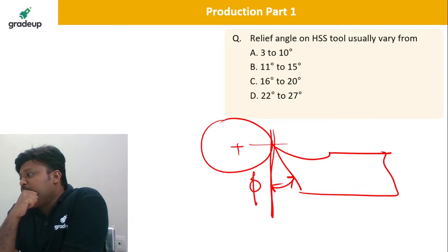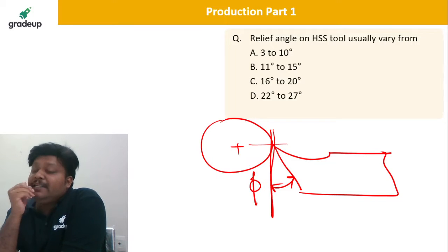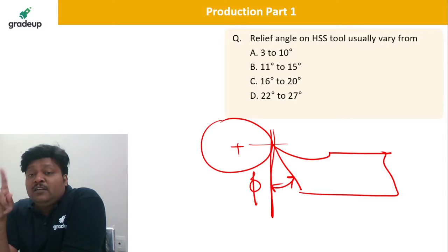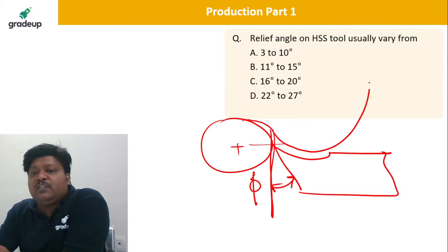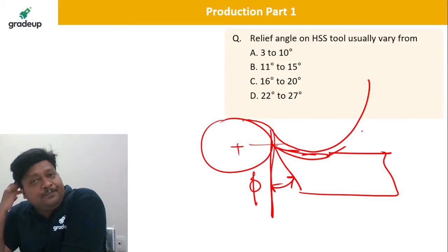Question is like this: tool cutting forces with increasing cutting speed will be, options are increase, decrease. So dear, definitely we can say that when the cutting speed increases, there will be very easy flowing of the chip over the rake face. So the friction automatically goes down, and there are no forces to slide the chip. It will slide very nicely. Again, the material is deforming very nicely at higher cutting speeds. So definitely it should be reduced, you can say.